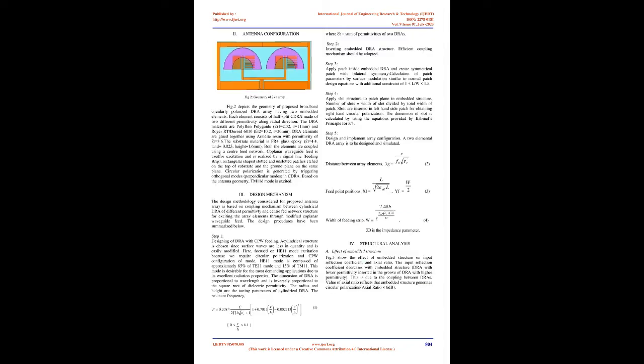Many applications such as WLAN, WiMAX, radar applications, and video conferencing require broadband operation. So DRA draws more attention as a resonator. Systems with circular polarization are insensitive to antenna transmitting and receiving configurations. Also, they are less susceptible to propagation effects, weather alterations, and interferences. Thus, designers focused more on circularly polarized DRAs for wireless applications.